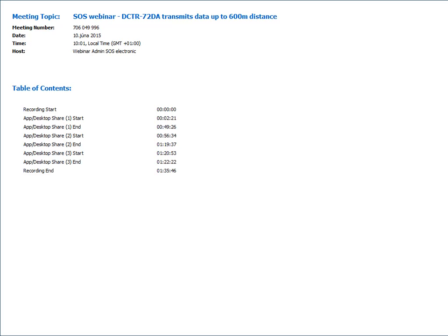The security is based on the MID, or the ID of the network, which is based on the module ID of the coordinator. That's why, when you want to replace the coordinator without new bonding, you need to clone the coordinator. And as I said, we are coming with AES next year.